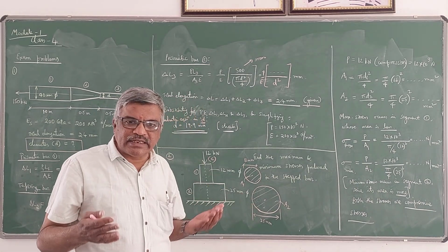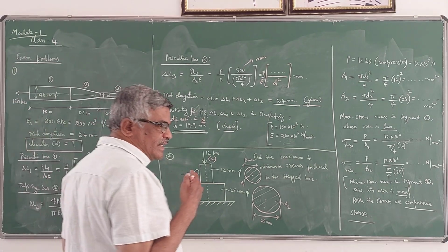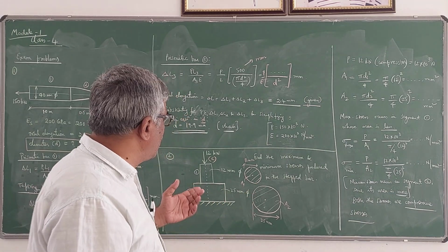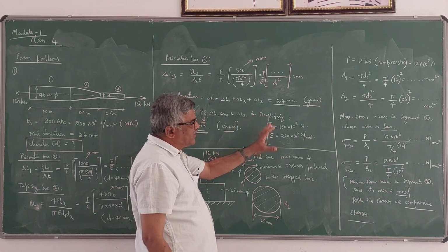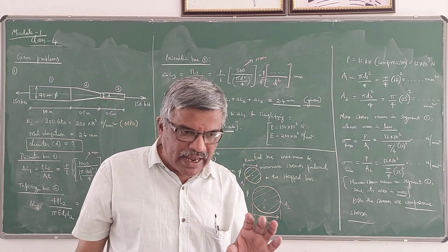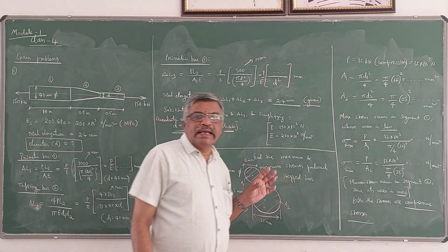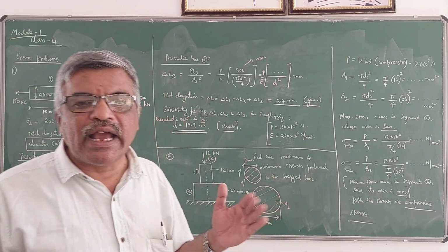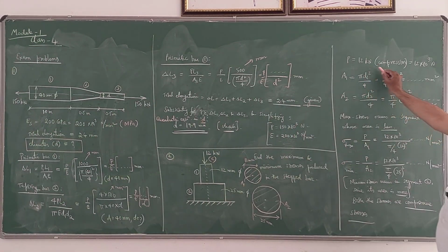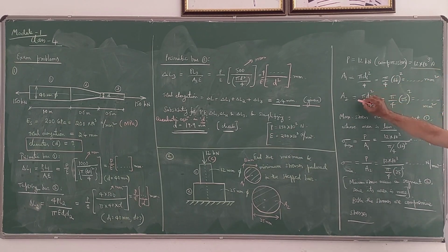So you know that stress is inversely proportional to area. If the force acting is same, then stress increases with decreasing area. Because area comes in the denominator, sigma is equal to P by A. P is the force acting on that particular member and A is the cross-sectional area of the member. If area is less, the stress will be more. So very simple concept. Here he has given P as 12 kN compression, that kilonewton will convert into Newton, then calculate A1 and A2.